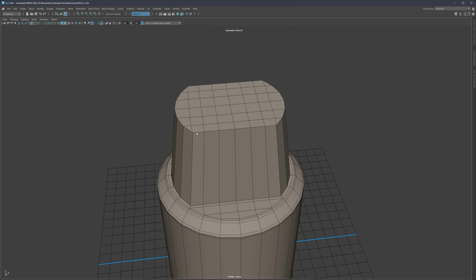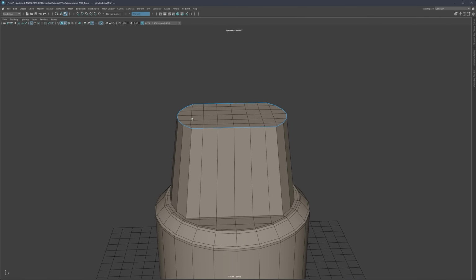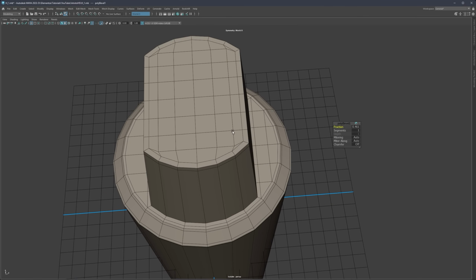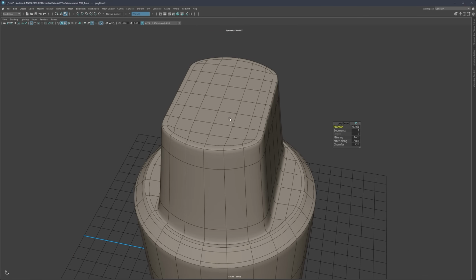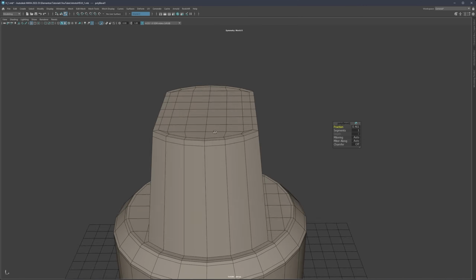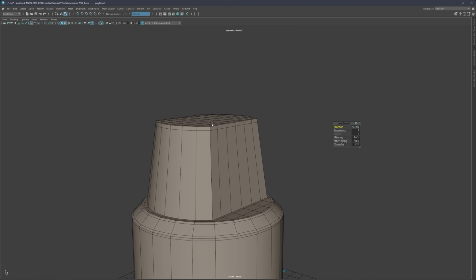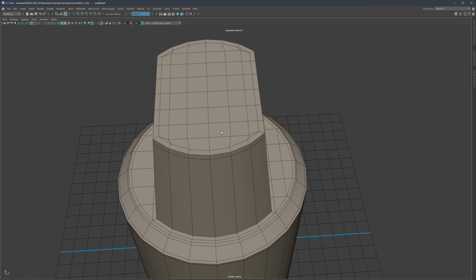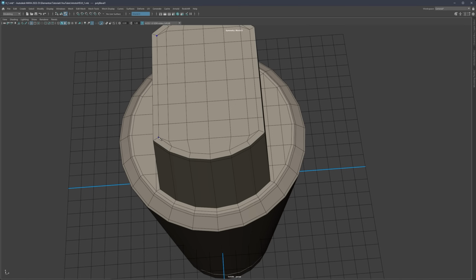All right, now what I'd like to do is create a small bevel here. So let's do a bevel and chamfer on, actually chamfer off. And there we are. And I think the curvature or the support loop is going to be just okay there. And the same thing here. It's a very, very good habit just to start cleaning these edges that are maybe a bit too curvy.